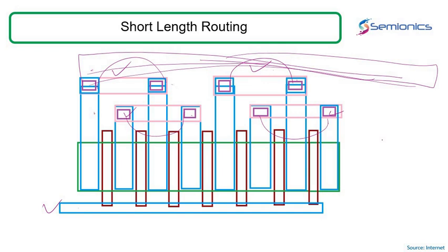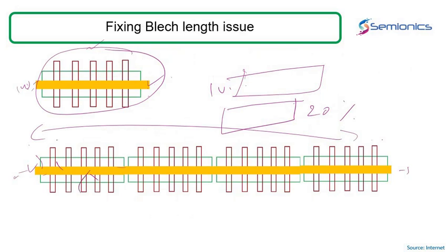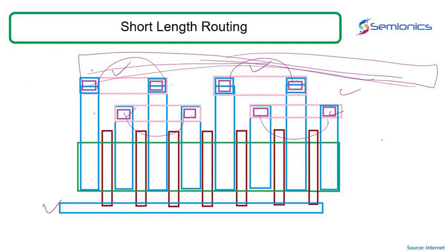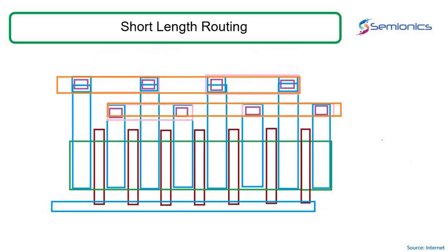Yes, you would do the same for the whole bunch of metal. Here I have shown one metal. Likewise, you would do the same replication for the remaining next set of transistors. But as and when you pull the metal, now I have moved from metal 1 to metal 2. I would have a similar connection over here. Likewise, I will move to a higher metal, something like this. It could be metal 3 or whatever, higher and higher.